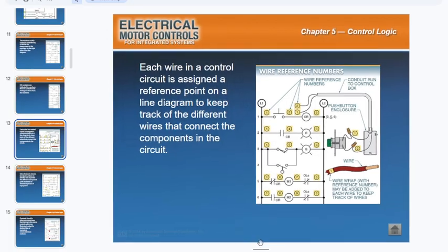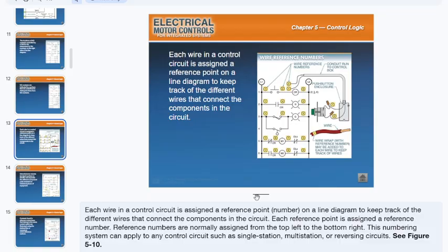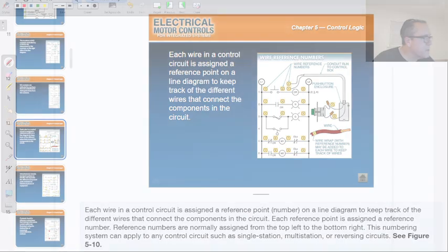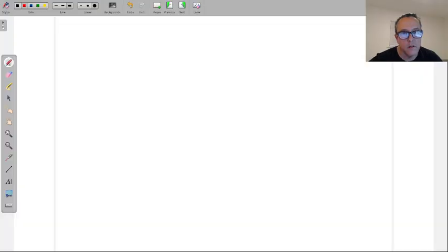After you've wired everything up, because you are now going away, right? Remember what I said earlier with that little dot in the middle that gives the person that's wired it up the opportunity to do whatever they want, in a sense. And when I go to troubleshoot it, it's hard for me to find this wire now because I don't know where they went to and from. Same thing with just even having to trace down a wire. If I even just needed to trace down a wire in a motor control circuit, as you are noticing from your labs, we don't use different colors. Every wire on a single ladder diagram is the same color. They're all blue, they're all red, they're all whatever was cheapest at the warehouse when we went to buy the wires today.